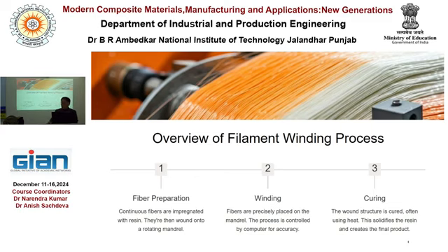It is very difficult manually, because constant tension is not possible. In real use, you will get unwanted residual stress, which is very undesirable. After the winding process, curing is needed.